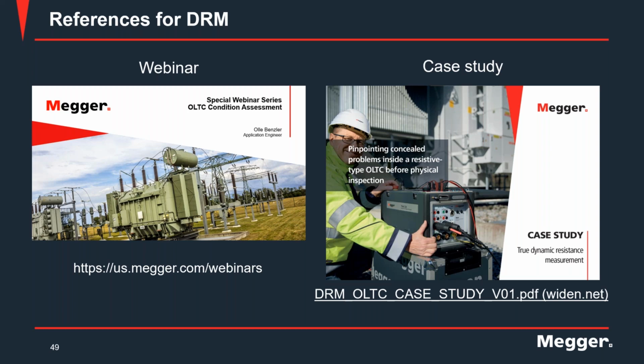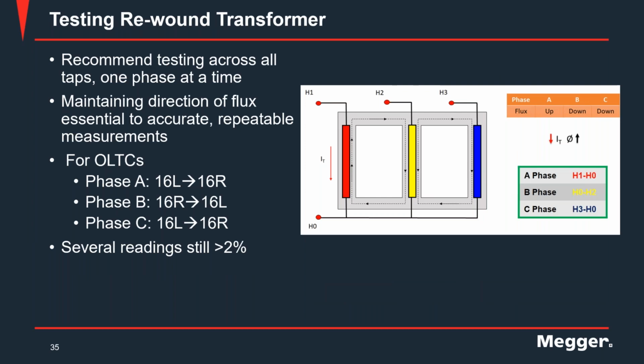Okay, that's a great question. I'll try to be brief. There are many factors. Starting with the short answer, it is not necessarily a requirement. There are solutions in the market to perform three-phase measurements. But in the case of a three-phase transformer, we have to look at the method that is used to accurately measure winding resistance.